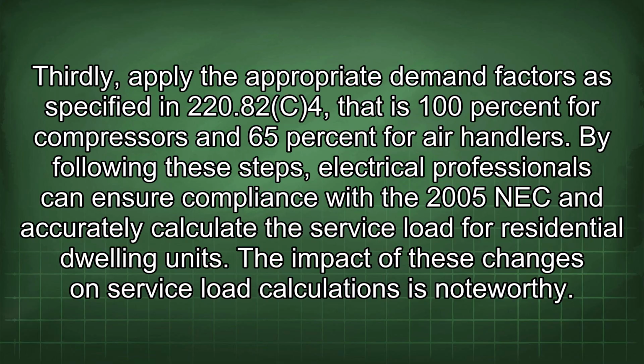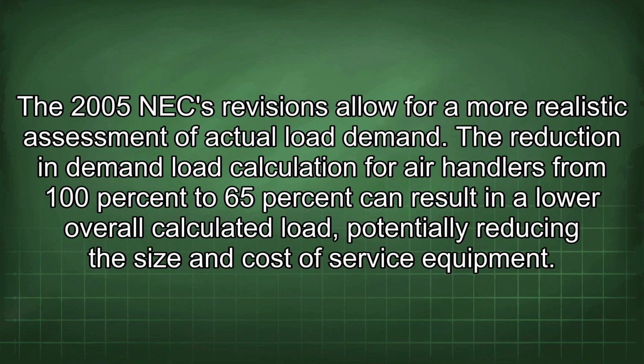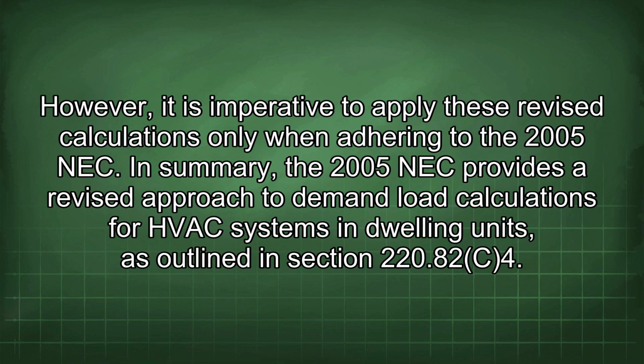The impact of these changes on service load calculations is noteworthy. The 2005 NEC revisions allow for a more realistic assessment of actual load demand. The reduction in demand load calculation for air handlers from 100% to 65% can result in a lower overall calculated load, potentially reducing the size and cost of service equipment. However, it is imperative to apply these revised calculations only when adhering to the 2005 NEC.